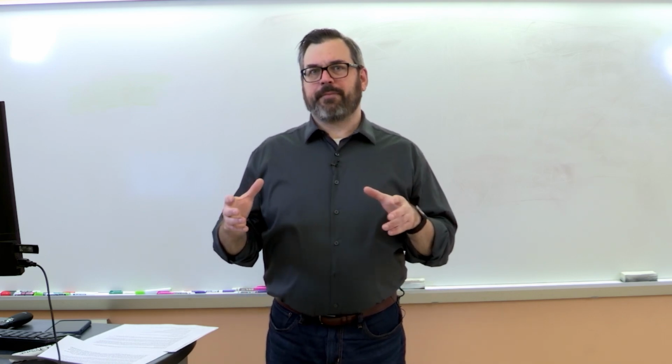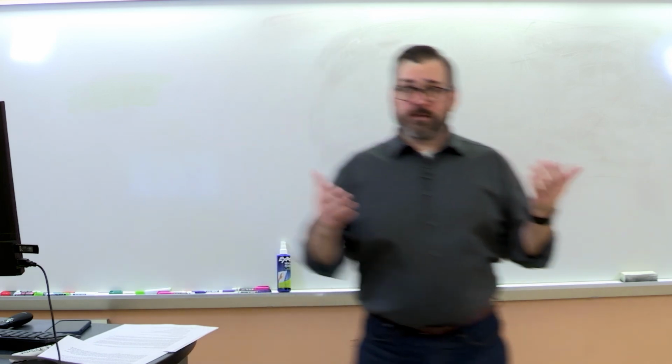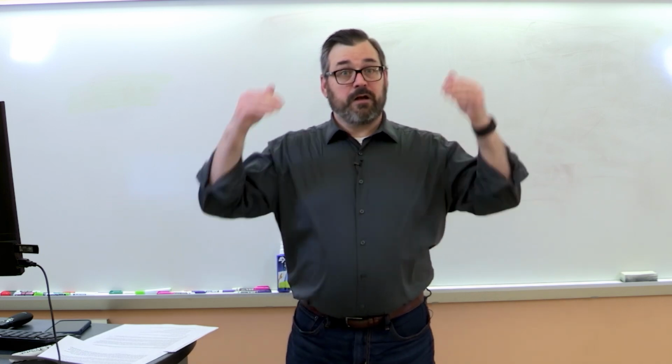But we have to consider that there are other forces happening, that there are lateral loads that would cause the side-to-side movement of a structure. Dancers don't just move up and down. They move this way, they move that way, and their motions impart lateral forces, which could cause a structure to move this direction, not just resist forces from up and down.